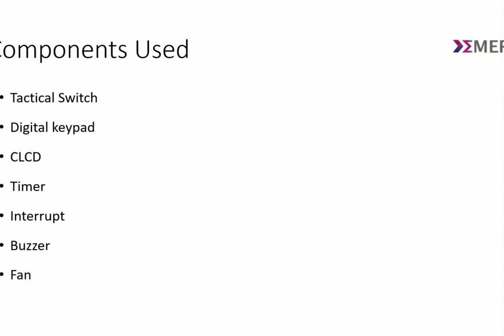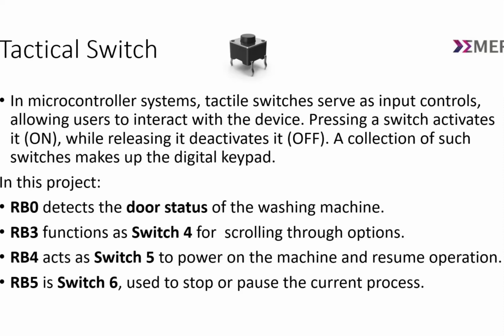Next we are going to see the components we have used in this project: tactile switch and digital keypad, CLCD, timer, interrupt, buzzer, and fan. Let's first dive into the tactile switch. Here is the tactile switch. In microcontroller systems, tactile switches serve as an input control, allowing the user to interact with devices. Pressing the switch activates it, like on, while releasing it deactivates it, like off. A collection of such switches makes up the digital keypad.